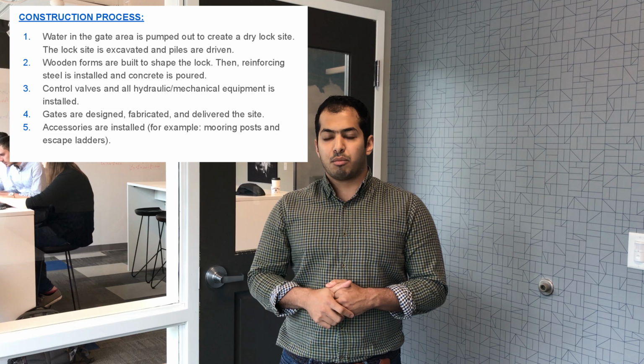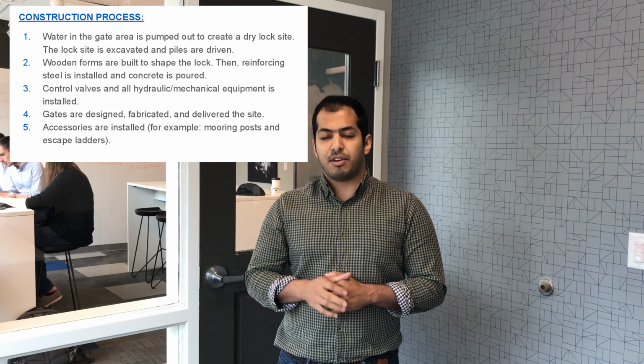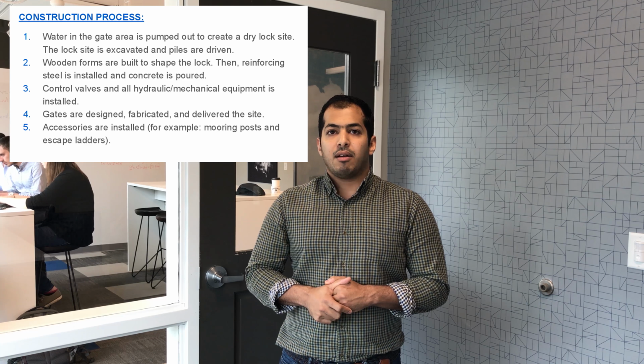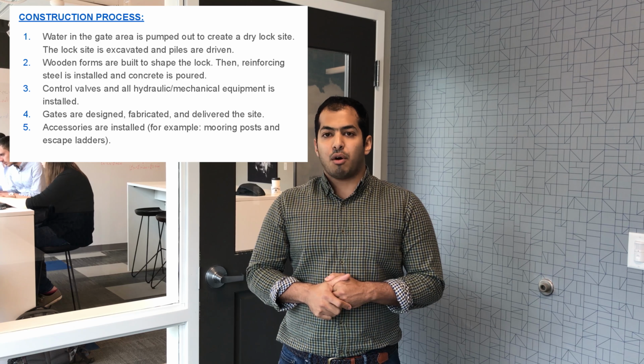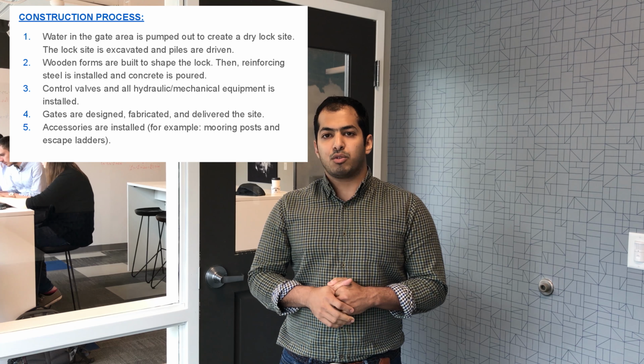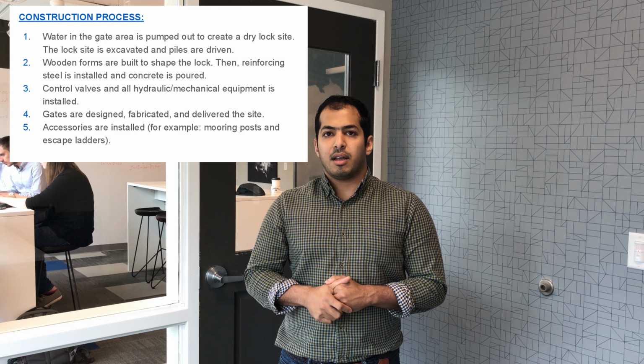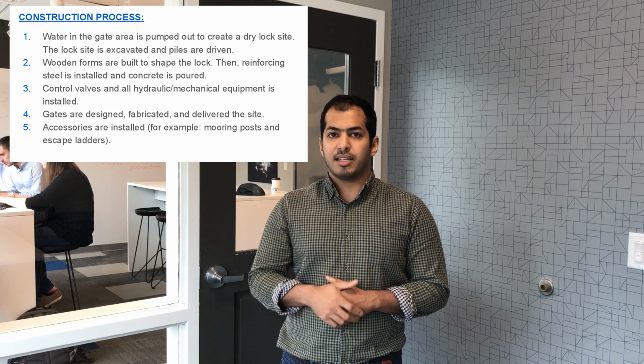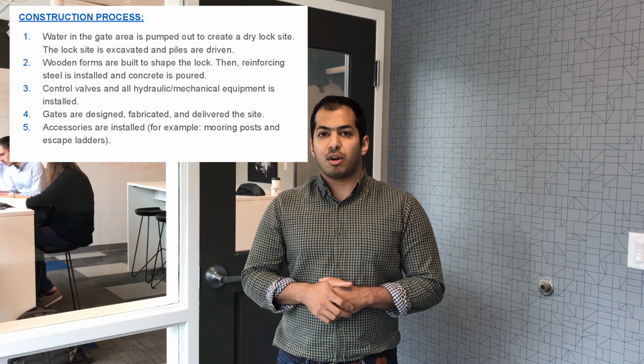After that, wooden form will be built on the site, and reinforced steel and concrete will be poured on the site. After that, concrete valves and all hydraulic and mechanical equipment will be installed on the site. Gates are designed and fabricated off the site and delivered to the site. Finally, installing all accessories like escape ladders.